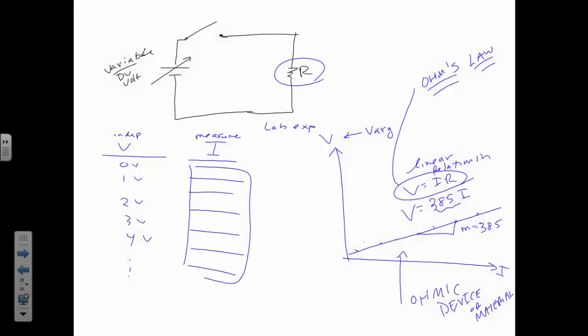These are 20 ohm resistors, and they're in this anodized aluminum package that looks literally like radiator fins, so I can suck heat off of it. Those are 35 watt power transistors. I can radiate 35 watts of energy off of that, which is a huge amount of energy. These are rated for 10 watts, which is still a lot. These get hot, but they're designed to be hot. That's designed to be even hotter.